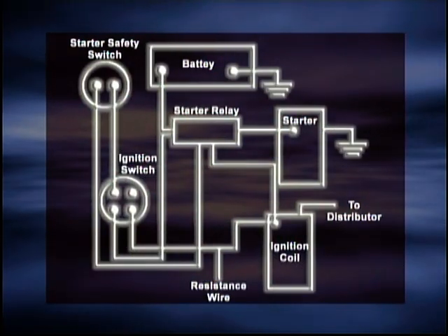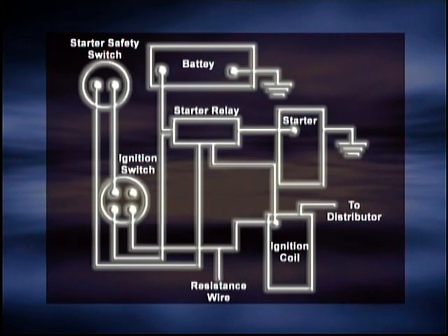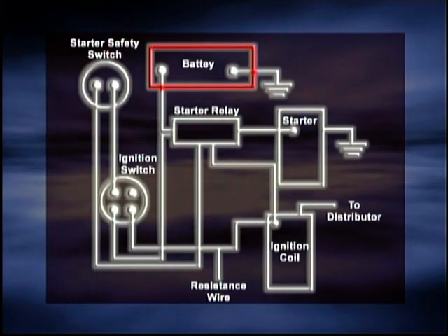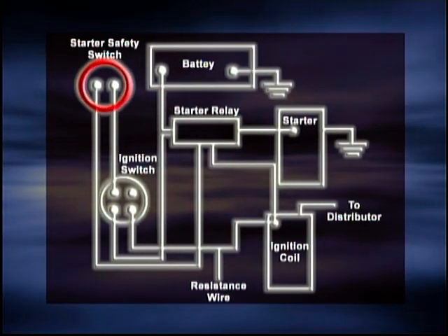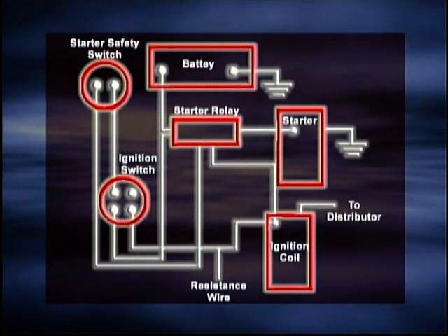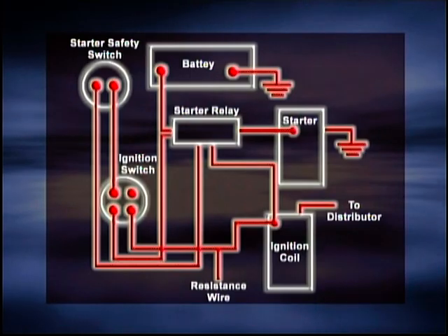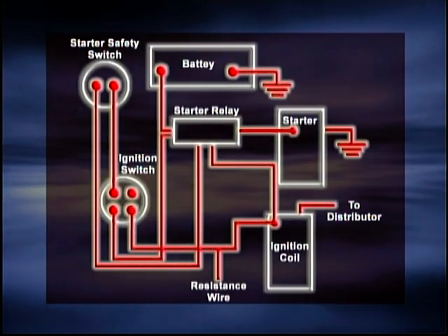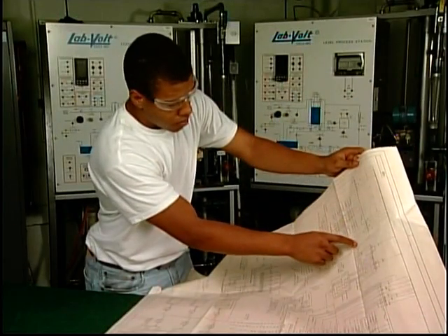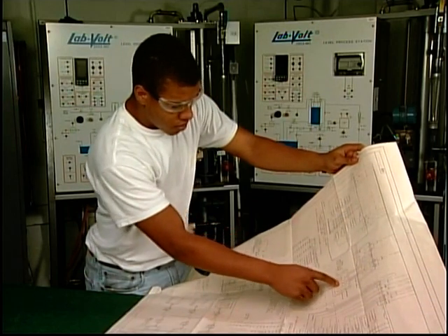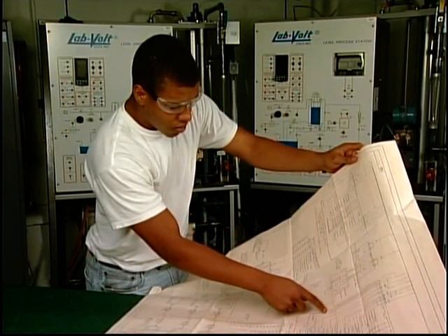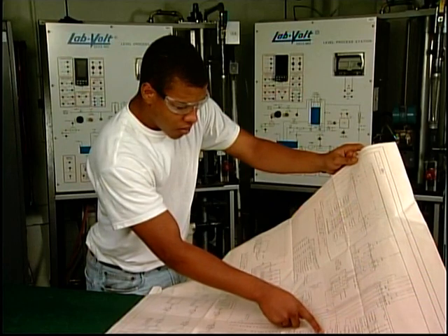A wiring diagram is similar to a pictorial diagram, except that the components are simply shown as rectangles or circles. The location or layout of the parts or components is in their actual position, and all connecting wires are shown connected from one component to the other. Wiring and layout drawings are used extensively by technicians in the construction and maintenance of electrical and electronic equipment.